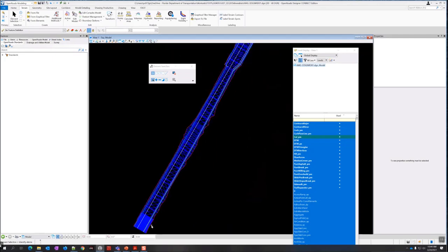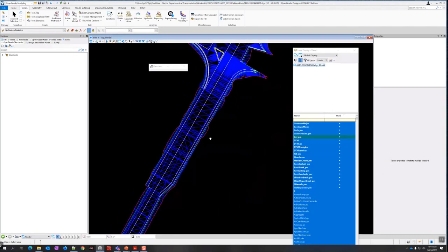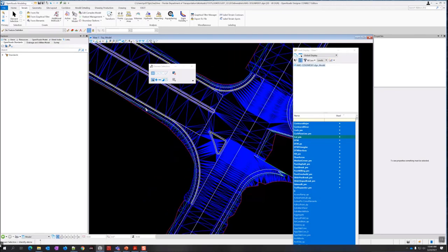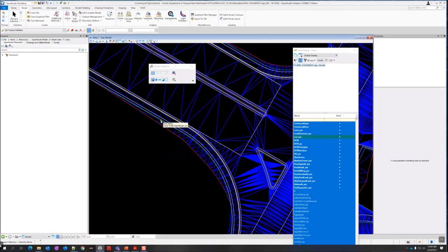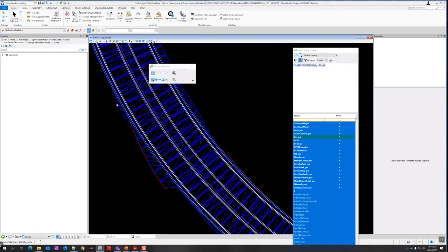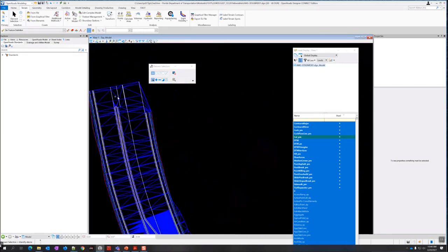Because those are, for the most part, the feature definition that we have along the edges. The only case would be, I guess, if you're not tying it with a slope, if you're tying like the back of sidewalk to it, you might not have that point. In which case you might want to look at what feature definition you're using at that point on the back of sidewalk. It probably also isn't going to hurt anything if you just add a cut or fill PM at those points. That's probably another option. That's just something in how you set up your templates, how you want to do it.